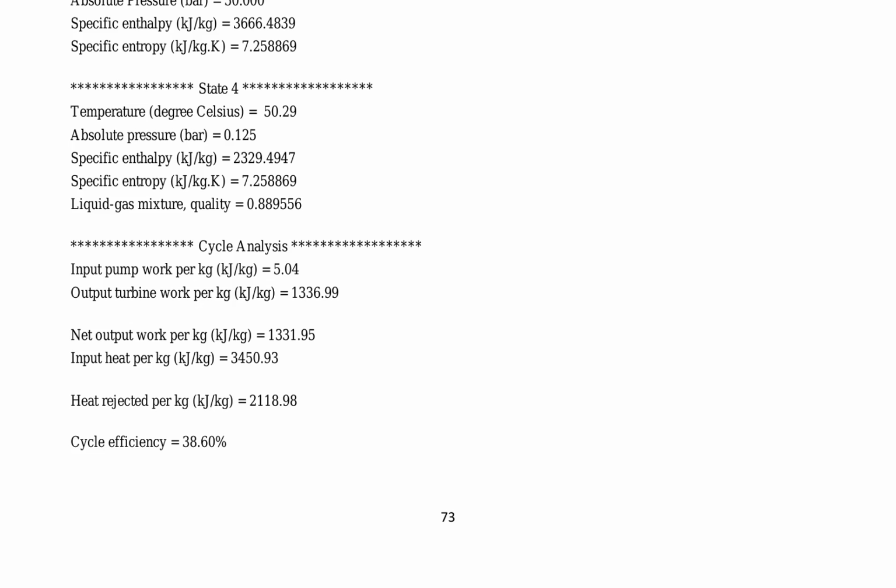State 3, on the other hand, exhibits a temperature of 600.00 degrees Celsius, absolute pressure of 50.000 bars, and specific enthalpy and entropy values of 3666.4839 kJ per kilogram and 7.258869 kJ per kilogram K, respectively.